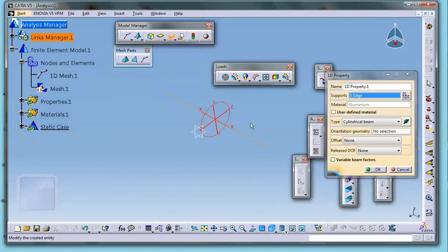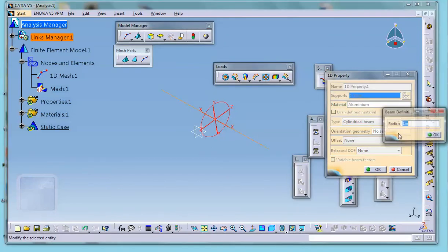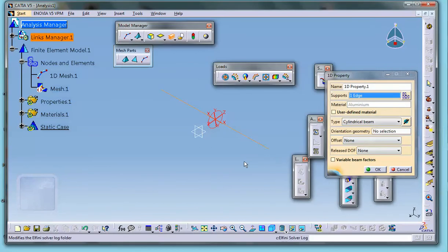Good. Now, there's something else that's important here, which is orientation point. Remember, when you have an I-beam or you have a rectangular cross-section, etc., the orientation of this will affect the response of the beam. If it's circular, it doesn't matter. A circle, you spin this, or you twist, you rotate, revolve this about the axis, nothing is going to change. This is why when you have a cylindrical cross-section, cylindrical beam or a tubular beam, you can actually close this. You don't have to select orientation geometry. We're going to worry about this in class next week.